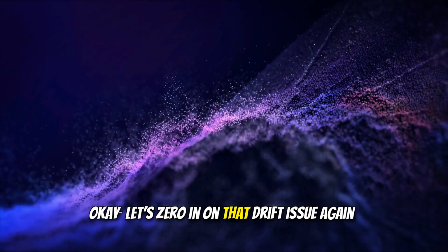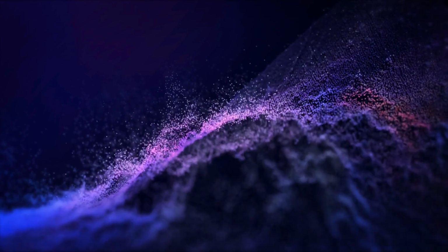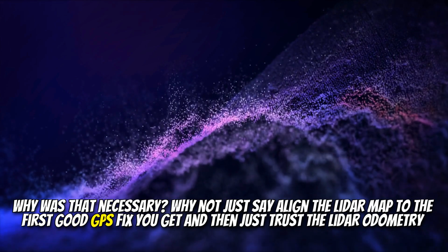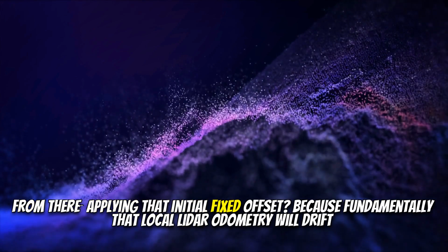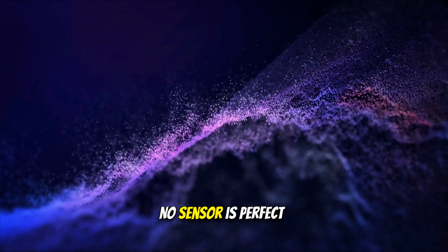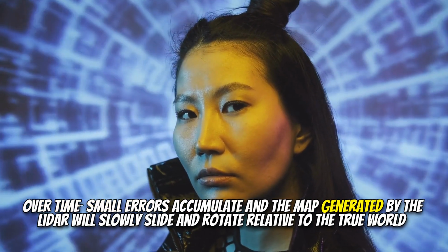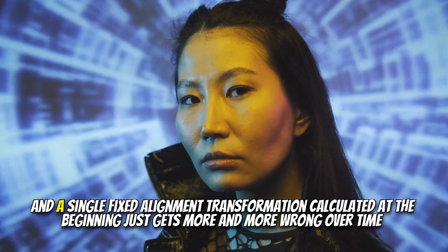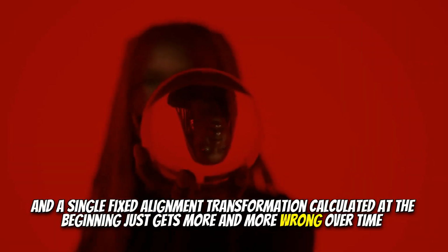Okay, let's zero in on that drift issue again. You mentioned they model the alignment drift using a random walk. Why was that necessary? Why not just say, align the LiDAR map to the first good GPS fix you get, and then just trust the LiDAR odometry from there, applying that initial fixed offset? Because fundamentally, that local LiDAR odometry will drift. No sensor is perfect. Over time, small errors accumulate, and the map generated by the LiDAR will slowly slide and rotate relative to the true world. And a single fixed alignment transformation calculated at the beginning just gets more and more wrong over time.